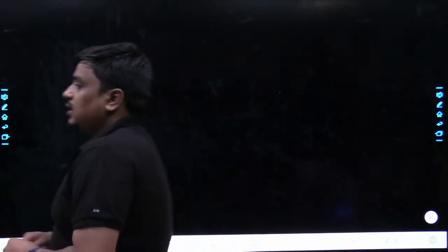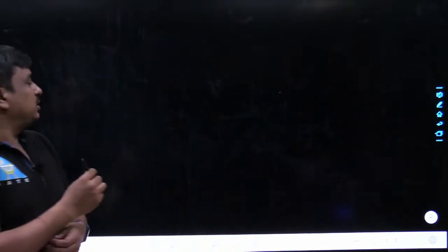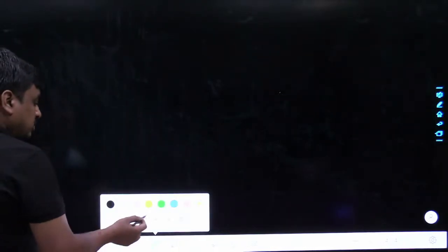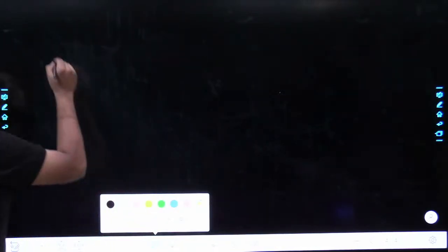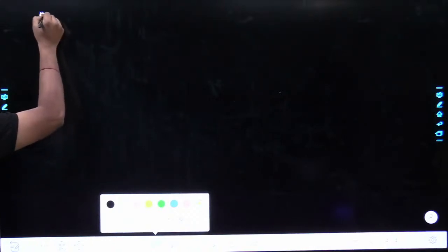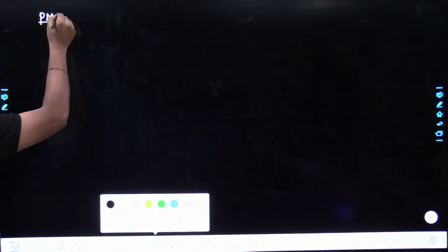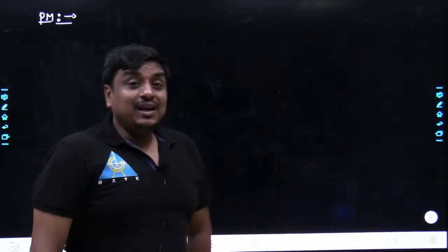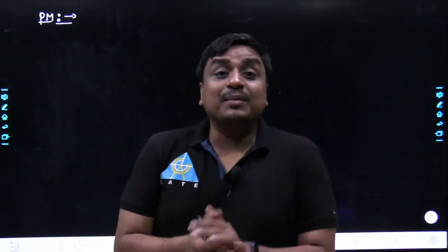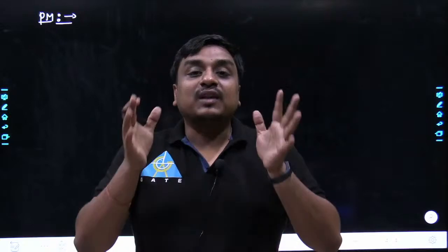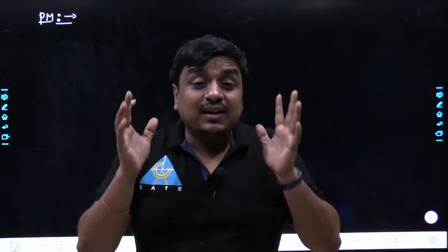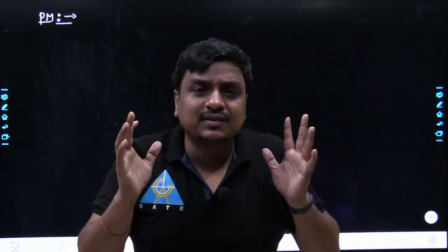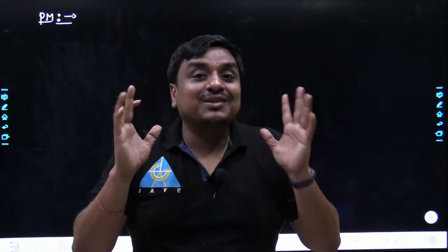Yes. So let me focus on the next two important terminologies, and they are nothing but phase margin and gain margin. See, what does it mean by the phase margin? The name itself is self-explanatory. It's a margin in phase. That means how much phase can be introduced within the system, while the system is still stable.